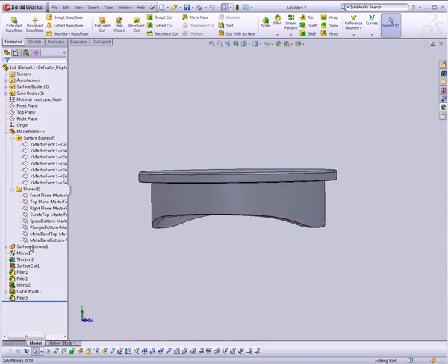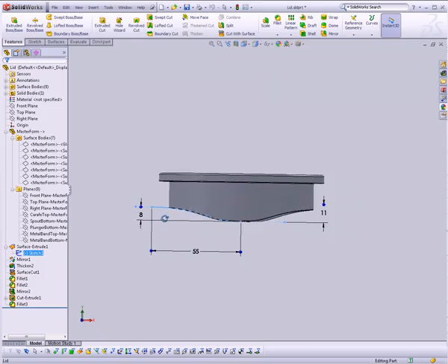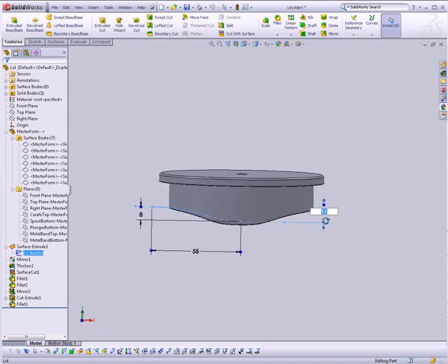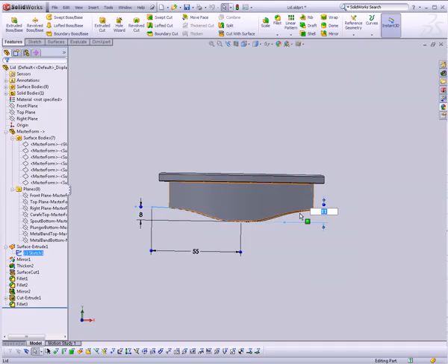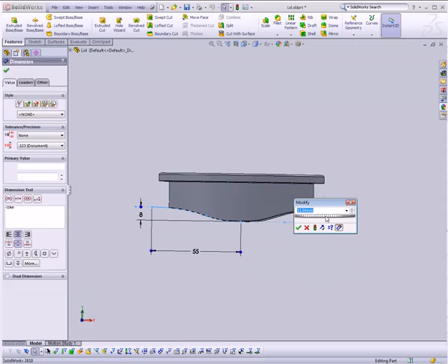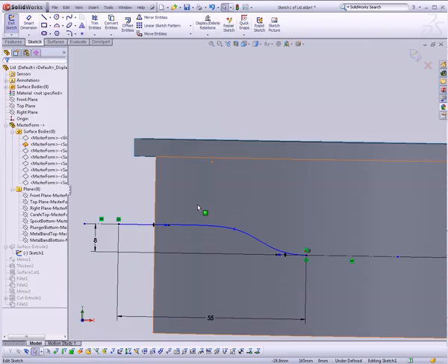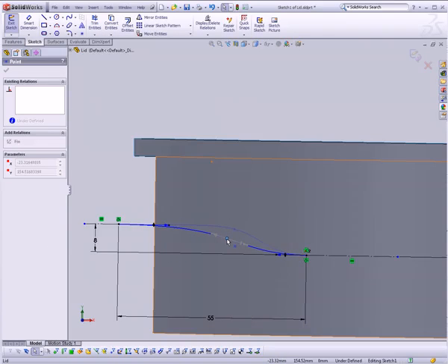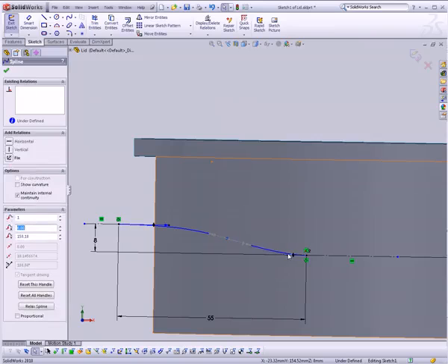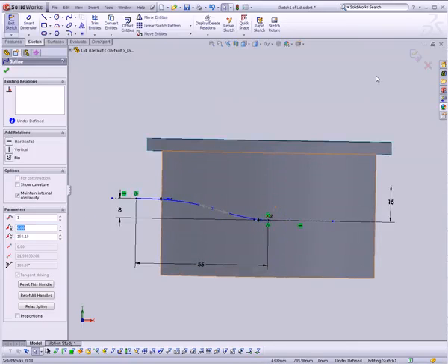Now I'm just going to edit the original sketch for the bottom surface we created. And right now, the bottom of it is 11 millimeters from the plane that we have. So I'm just going to go ahead and change that value. Let's make it 15 millimeters. Hit Update. See what that does for us. Okay, that'll be a little bit better, and now we can just edit the actual sketch to kind of fix that shape, because it got a little bit too sharp there. That should be a little bit better.